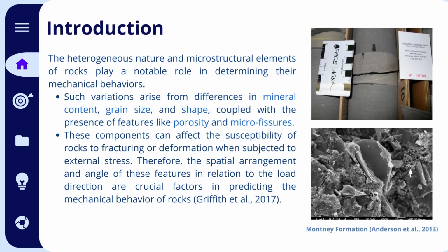Rock's mechanical behavior is influenced by their diverse composition and microstructures. This diversity comes from variations in mineral content, grain size, and shape, along with factors like porosity and microfissures. When external stress is applied, these elements can impact how easily rocks fracture or deform. As Griffith and his colleagues have shown, the arrangement and angle of these features related to the applied force are important factors in predicting how rocks will behave under stress.